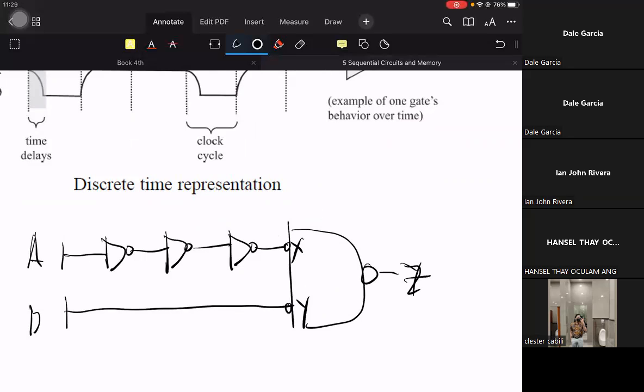But if it is only combinational input-output that we want, delay does not matter. But if we intend X to be delayed slightly compared to Y, let's say A and B come from the same input. What if each NOT gate introduces at least 1 nanosecond of delay?